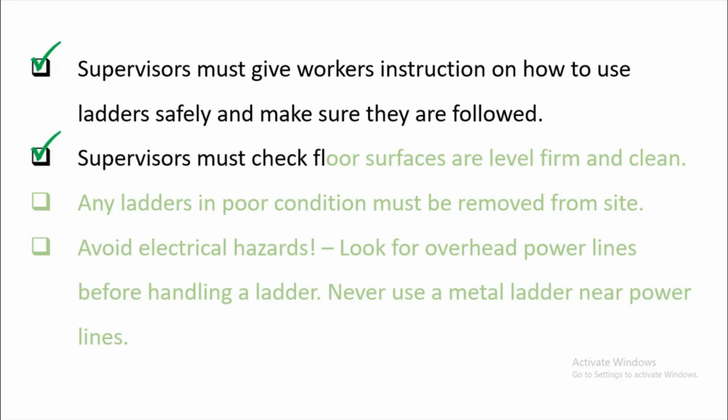Supervisor must check floor surfaces are level, firm, and clean. This is very important. Remember that your ladder is sitting on the floor, so if your floor is not level, you cannot make your ladder level, and if your floor is not firm, then there's a chance that it will sink, or your ladder will be sinking.